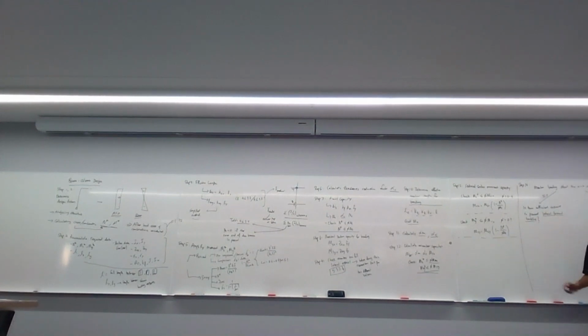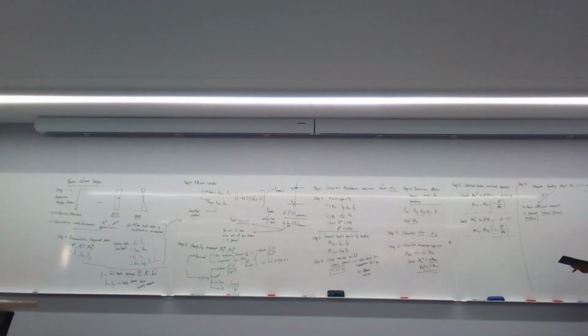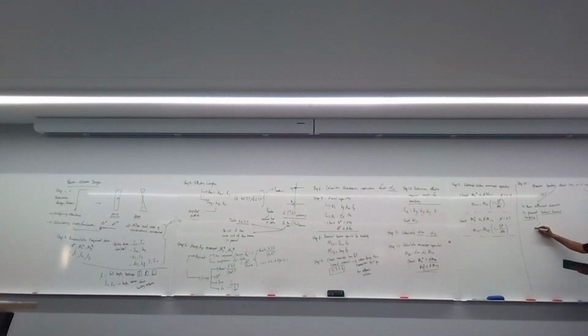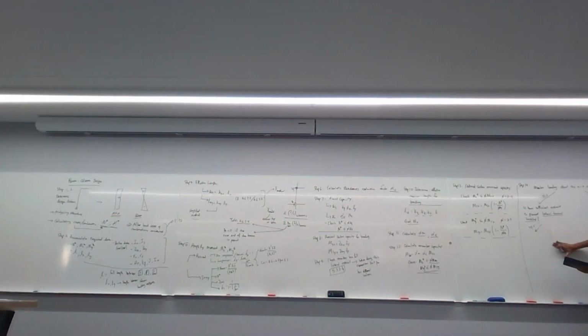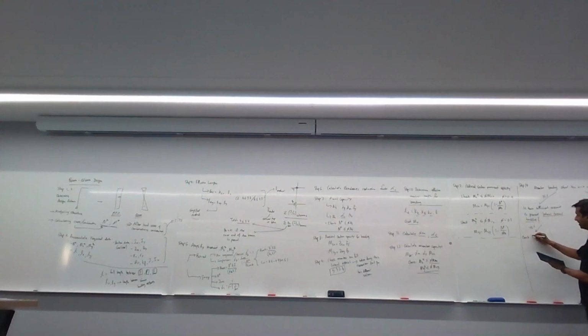Basically, what I'm asking here is MB equal to MS? Right? Is it continuously laterally restrained, or is it not? If MB is not the same as MS, then there's a yes, no here as well. So if this answer is yes, I'll write this down first. Then you check in plane